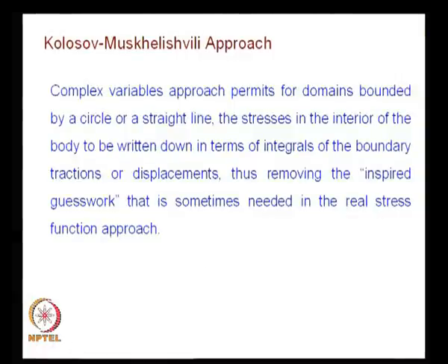The idea is this: in our stress function approach, we have always said how do you coin the stress function is important. We have said we would coin a stress function and go and investigate which problem it represents. We are not really looking at the problem from satisfying the boundary conditions, you are not evaluating the stress function. We are having only a semi inverse approach.